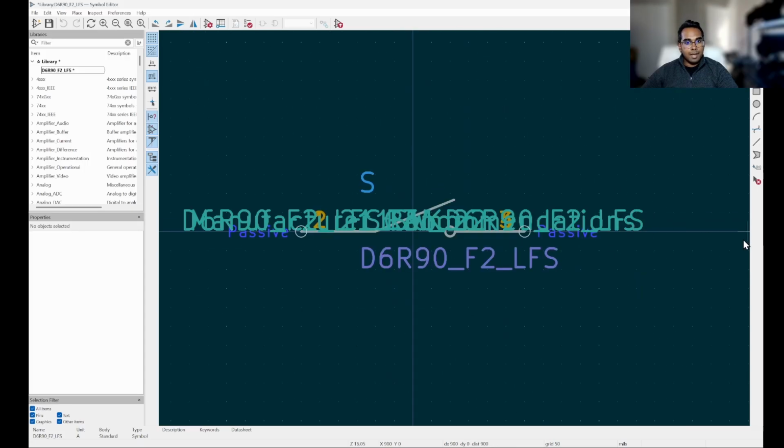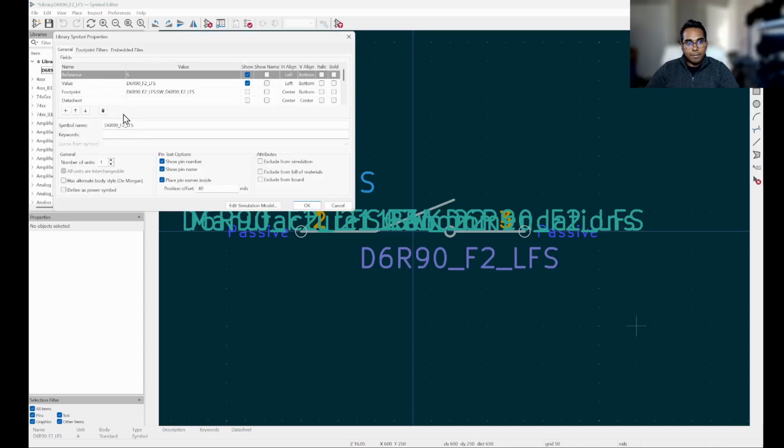Now, by default, I don't know why this is, but a ton of different manufacturers and design companies make footprints or symbols in KiCad that are just really jumbled and have things all over the place. So we can go in and clean this up before we actually want to use it. Double-click on the white space around this before you actually click and drag anything around.